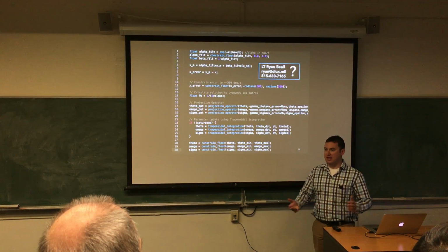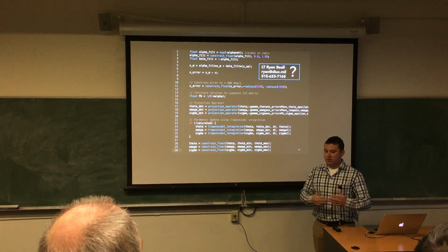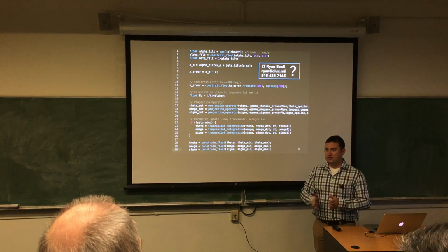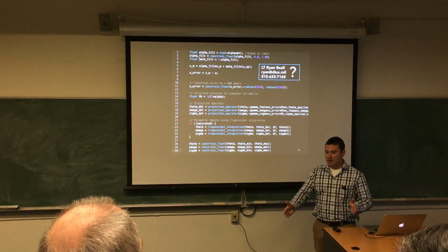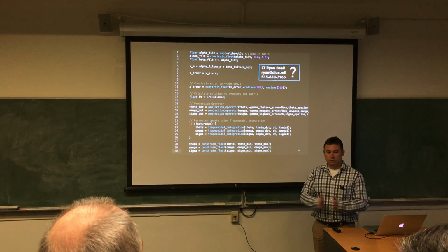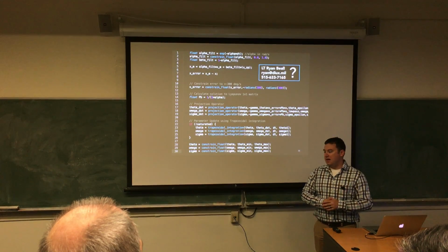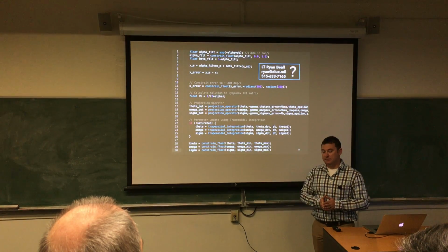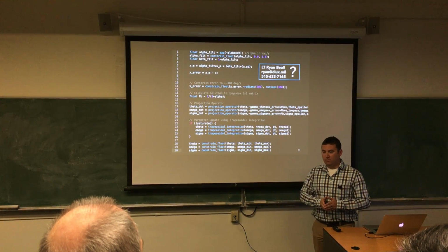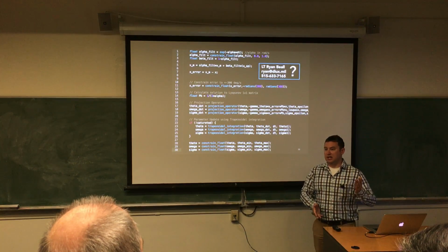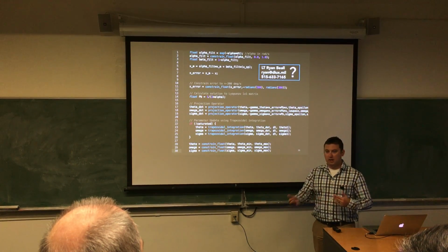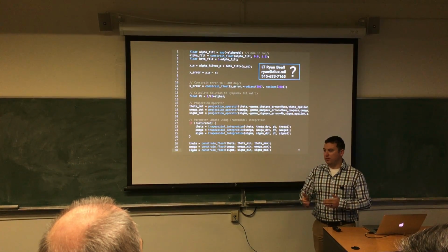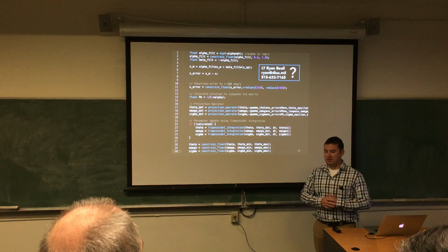It's significantly outperforming. So kind of the road ahead is this autopilot is limited to 400 hertz, and whenever you discretize anything mathematical, you want to make that loop frequency as fast as you possibly can. And 400 hertz is okay. I proved this algorithm runs at 50 hertz, but realistically, you want to be running in kilohertz or even higher. So the newer autopilots that are coming down the pipe should support that, but I proved the lower limit of 50 hertz, which is very low.